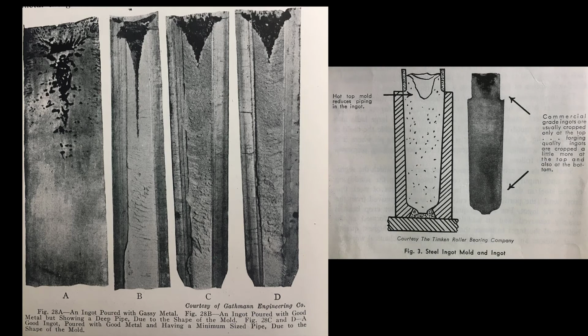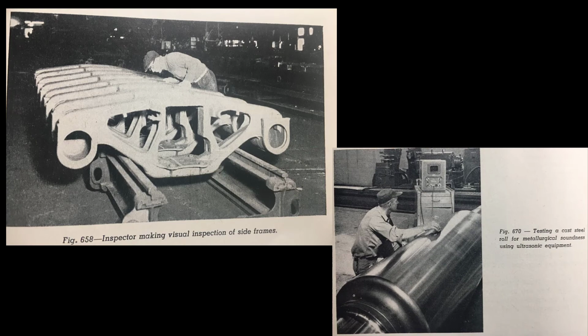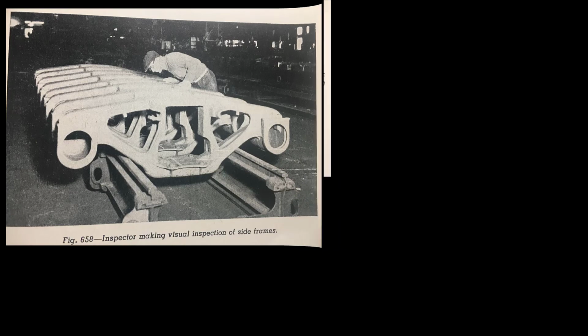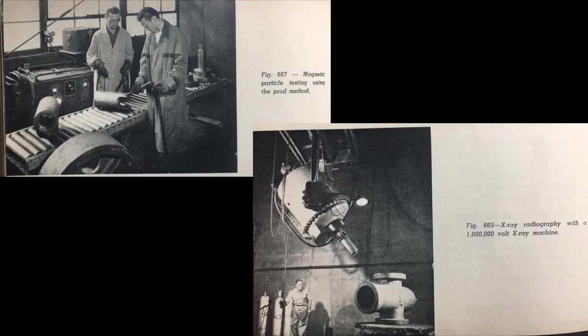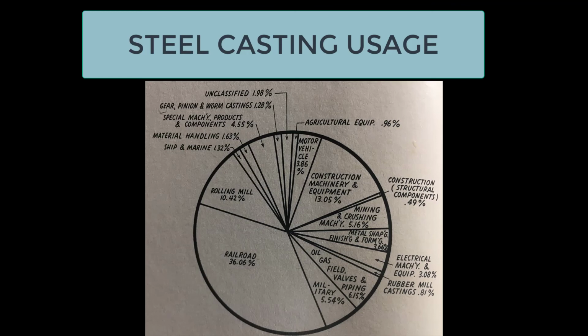Let's talk about casting defects. These can come from having a pour temperature that is too low. This causes the metal to solidify early. When the metal solidifies, the rest of the molten metal can't get past it, so it's not going to fill up the mold correctly. This is one of the few casting defects that you can see visibly, right? The part will just not be the right shape. Some other defects are voids, which are caused by the same thing, except they're internal, right? So you can't see them, not super good.